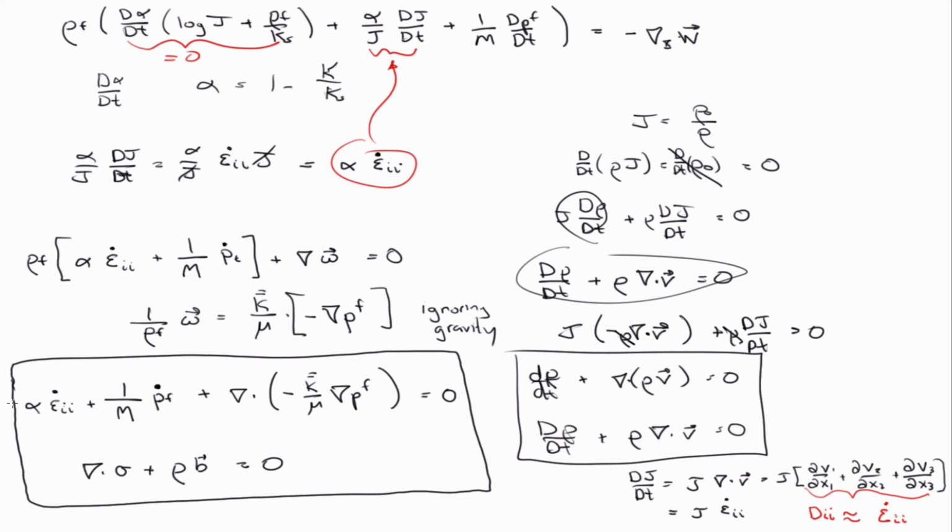And stress is a function of strain, which is a function of displacements, so you also have displacements here. If I plugged it all in terms of displacements, you'd have this equation. Remember, this is a stress that is the effective stress minus the pore pressure, right? So you'd have displacements and pressure in this equation and displacement and pressure in this equation.